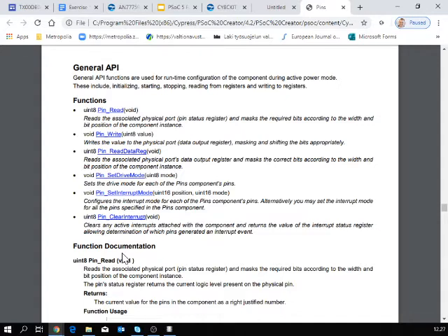For example, the one wire has the pull up resistors, and then you just drive it low. For setting it low, you can play with the set drive mode to have a constant 0 as your initial data register value, and you pull it down by setting the drive mode to strong for the time when you are driving it to 0. When you want to release it, you just put it to pull up or high Z.